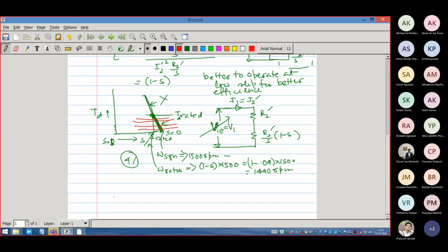So then what happens is that due to the variation of the external torque, as the machine characteristics is like this, and you have already chosen a voltage and a synchronous speed, omega sync, corresponding to 1500 rpm, essentially you are developing a characteristic like this, out of which you do not operate here, and let the torque vary only in this portion.